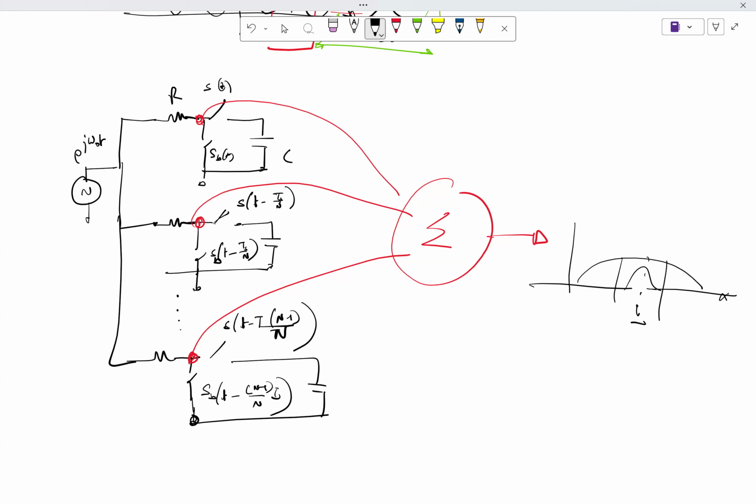So you can have a lousy LTI bandpass filter upfront. But the job of that bandpass filter is not to differentiate between signals which are very close to omega s and omega s. Its job will be to differentiate between the harmonics, or n harmonics, of omega s and omega s, and that is a much easier thing to do, right?